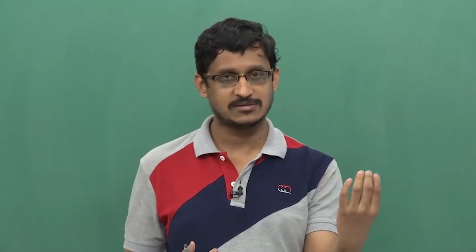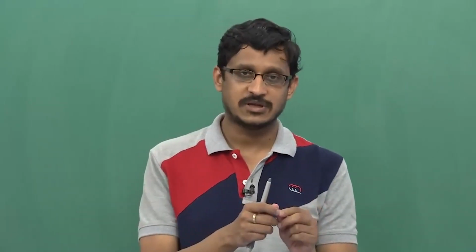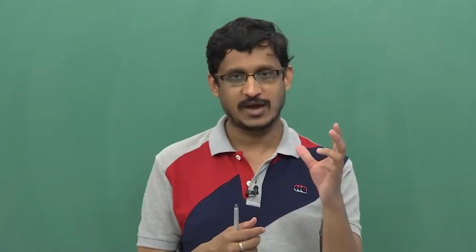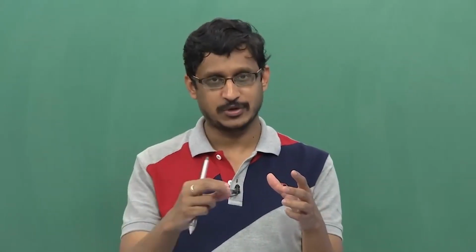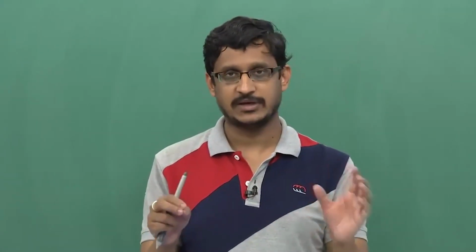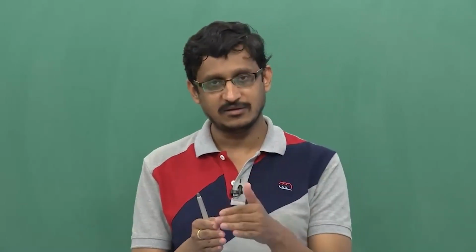So, there has to be a laser to fiber coupler. And sometimes this comes with a package. Most of the time, you have a laser diode emitting light, there is a micro lens which focuses light onto a pigtail of the fiber. We call this a fiber pigtail, which then completes the laser diode. That is to say, the optical source comes with a laser diode, a lens and a fiber.